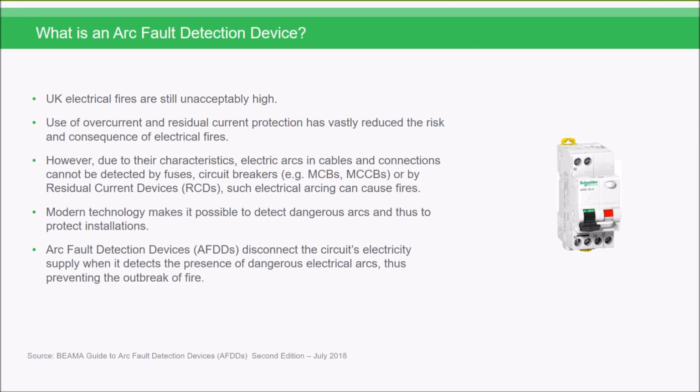And there are European installation standards, the IEC 60364. It recommends the use of AFDD devices to protect against arc faults in final circuits. Now, within the 18th edition as well, we mentioned that there is a recommendation, and the areas that we listed were around locations with sleeping accommodations, so whether it's hotels, nursing homes, bedrooms in homes, locations with risks of fire due to high quantities of flammable materials. So these could be barns or woodworking shops or where there's stores of combustible materials.